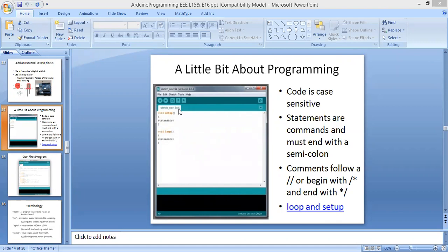The void setup function will execute only once, and after finishing execution of the setup function, execution will go to the loop function. If we are doing LCD interfacing, LED, or ADC interfacing, or displaying or printing anything, we have to write this statement in the loop function. If we are giving a delay between 2 functions, then we give the delay in numbers, and that value is taken as milliseconds. If we write 1000, that will be taken as 1000 milliseconds.